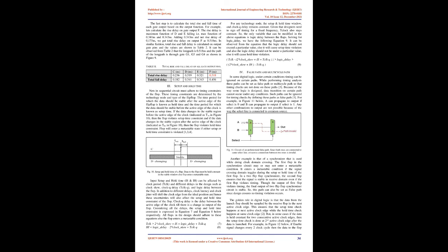Setup and hold time. Nets in a sequential circuit must adhere to the timing constraints of the flop. These timing constraints are determined by the technology node and the type of the flip-flop. The time period for which the data should be stable after the active edge of the flip-flop is known as hold time, and the time period for which the data should be stable before the active edge of the clock is known as setup time.